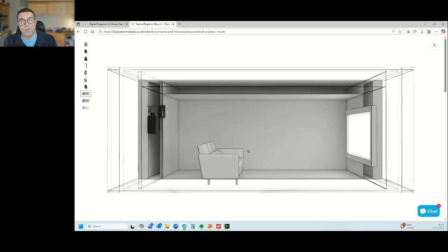Something I always like to use to put that in context: a human sitting in the theatre is about 350 to 400 BTUs. If you do a thermal system, just an AC system for the cinema, with the projector in the cinema, it needs to handle however many seats you've got, plus 10. That's how much loading minimum you've got to have in the AC system.